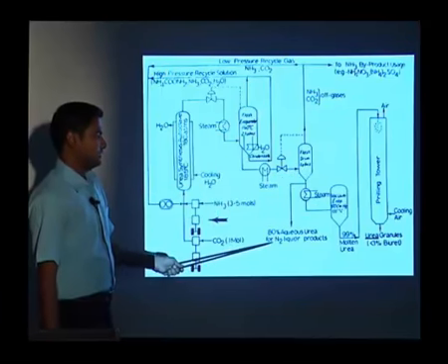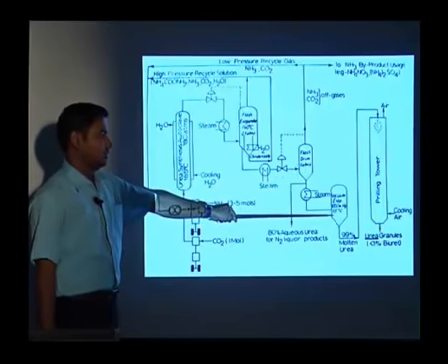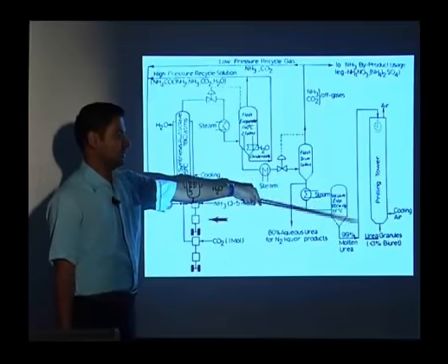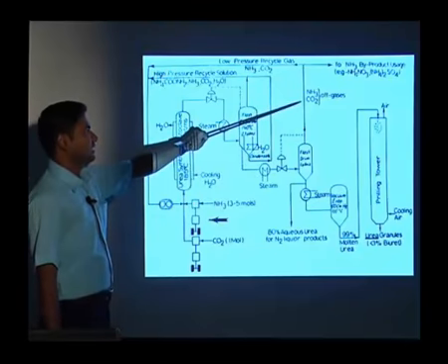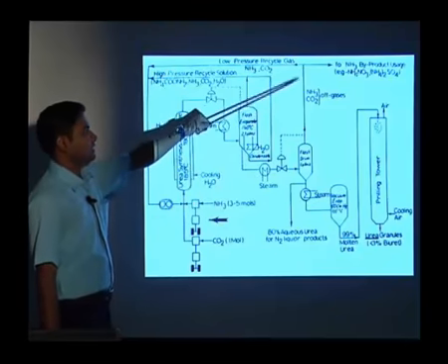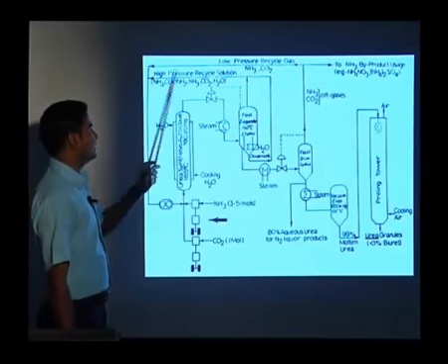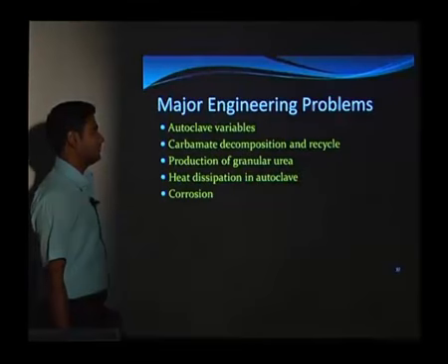So it is sent as aqueous urea or molten urea. We can have the vacuum evaporator, where we get 99% molten urea, which can be prilled in the prilling tower. Whatever NH3 and CO2 off gases there are, they are sent to NH3 byproduct uses, or they can be recycled back to get more conversion to form urea.